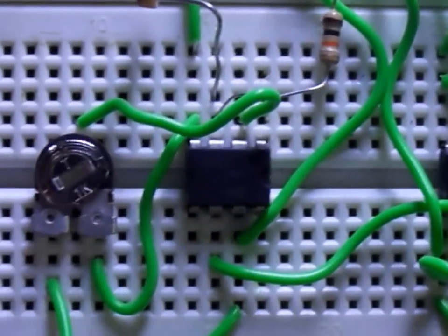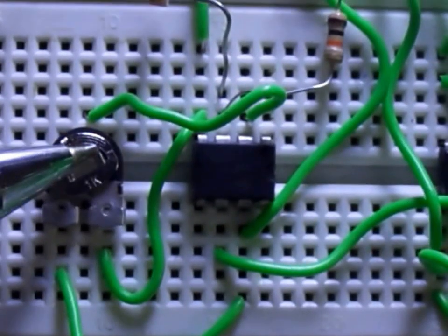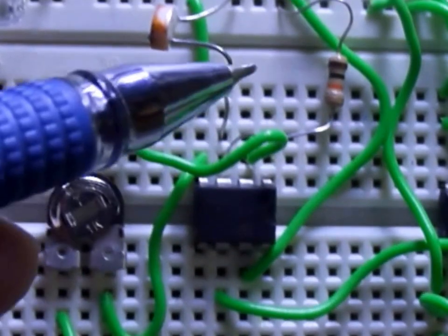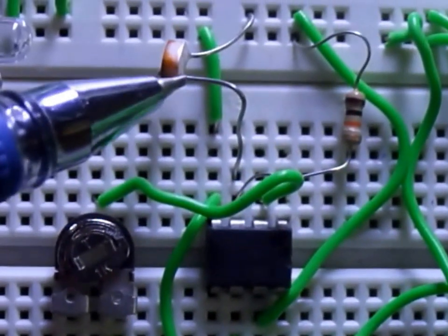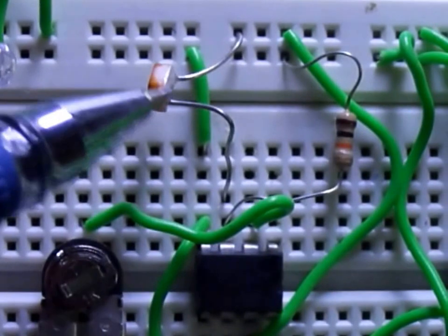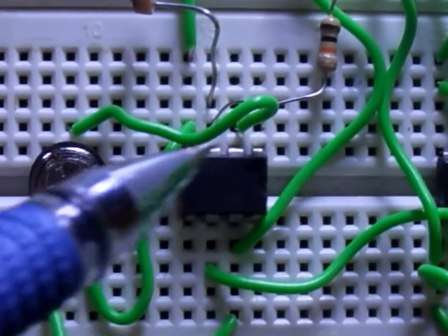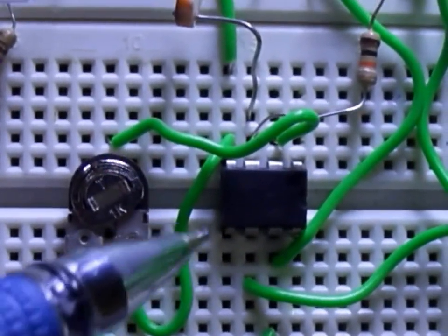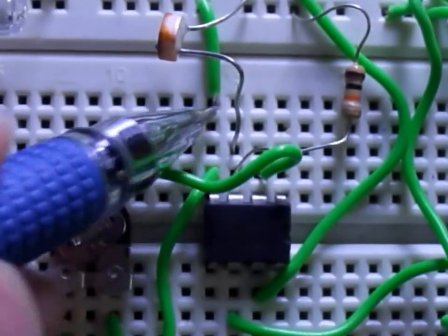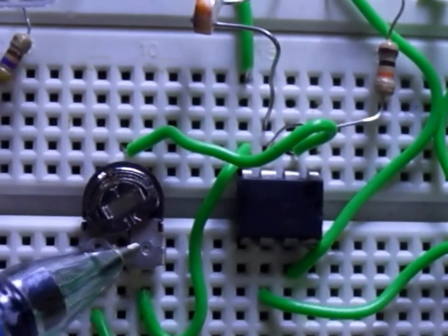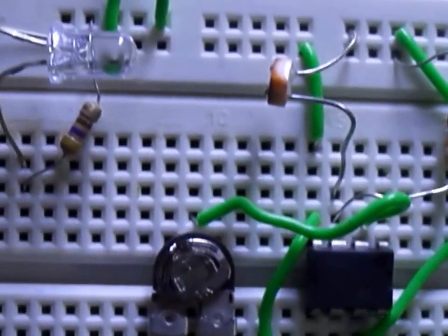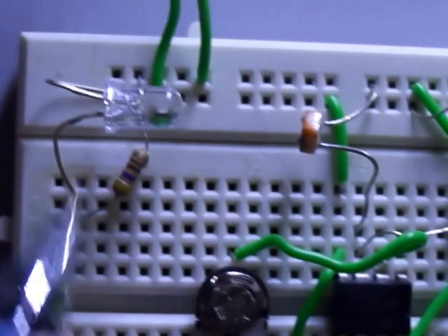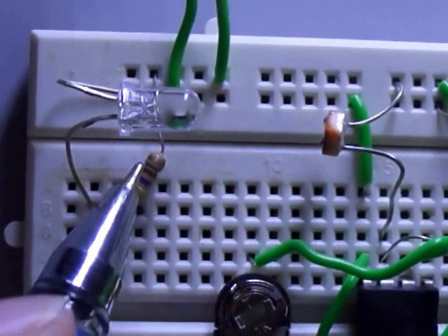as was mentioned in the data sheet of IC741. Then the output from the potentiometer is connected to pin number 2, and the output of the potential divider that is built from this LDR and this resistor is into this pin number 3. Pin number 4 is grounded, and you can see this is ground, and the same ground is connected to this potentiometer. Well, this is the LED, the white LED, and this is a 470 ohm resistor connected to it.